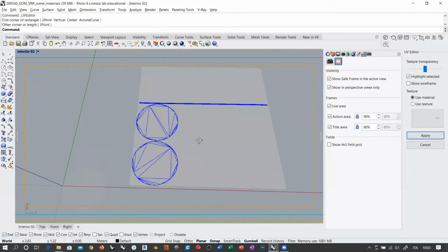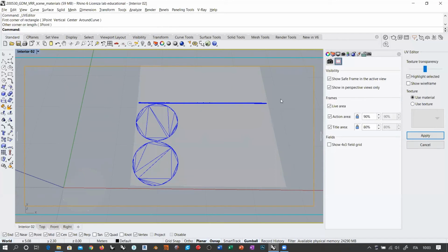So why do I say that Rhino, yes, allows doing some unwrapping and texture mapping, but it's not the best option? Because you don't have absolute control over the topology of the mesh. And so you will most likely get these kinds of weird meshes with a huge amount of triangles, with polygons that have absolutely variable size and aspect ratio.